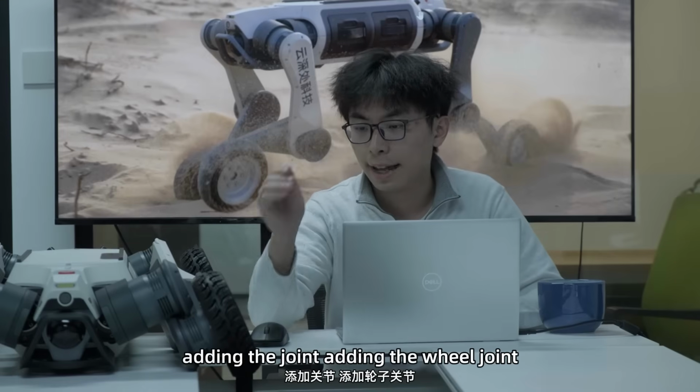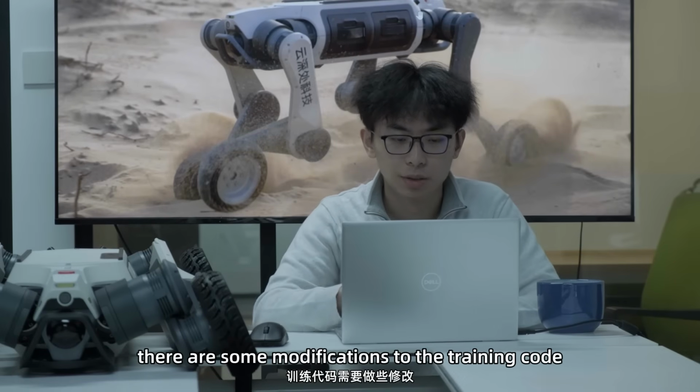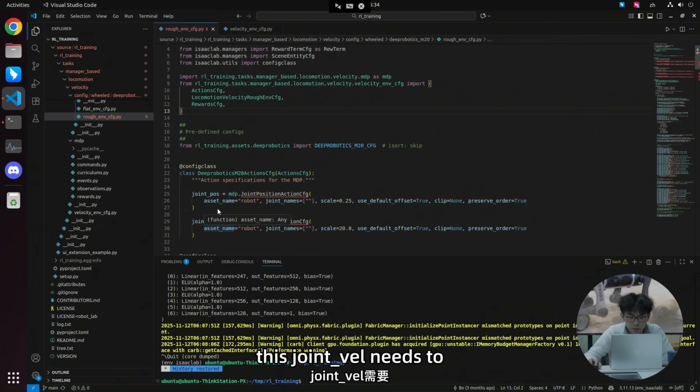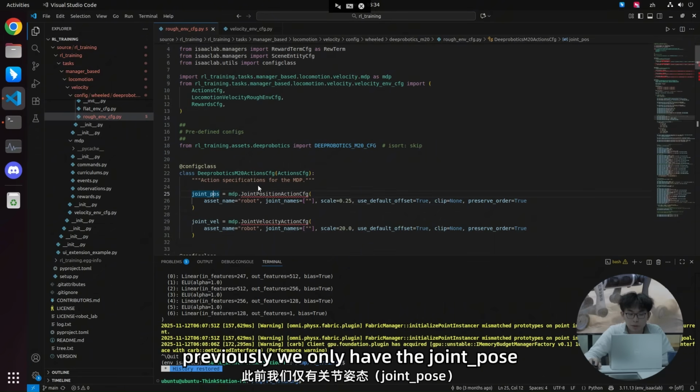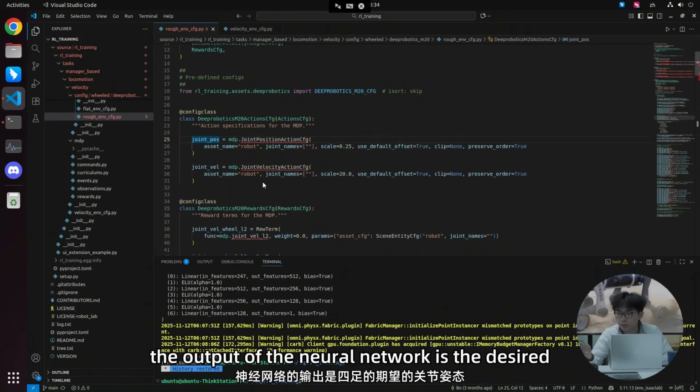For adding the wheel joint, there are some modifications to the training code. The one big difference is the joint velocity. Previously we only had the joint position, because the output of the neural network is the desired joint position of the quadruped.